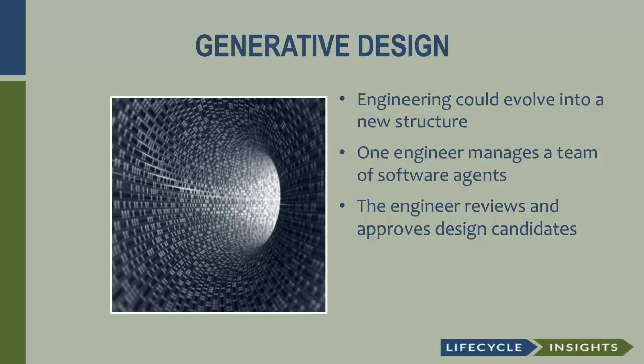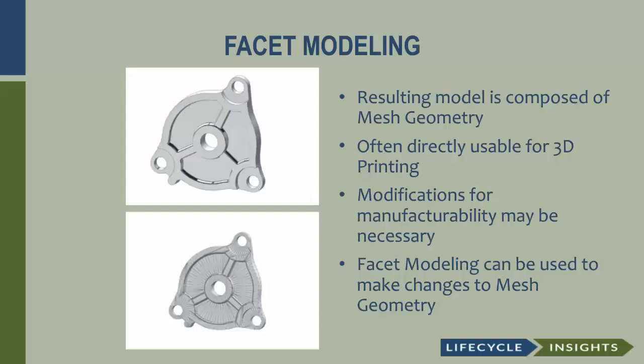Now, something to take into account. When you look at how this technology works, it's based on finite element analysis, right? We kind of know that. And when you remove an element from that model, you're going to end up with jagged edges, right? So as you do that over time, you're going to end up with something that's kind of a lumpy model, right? And when you think about that, it's actually called mesh geometry, as opposed to an exact boundary representation that is all smooth, okay?